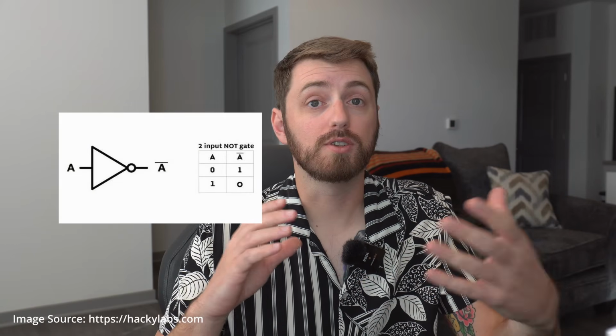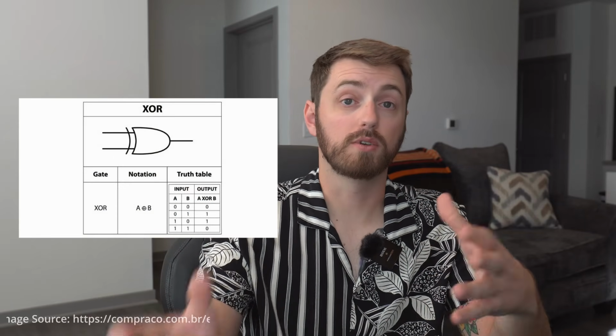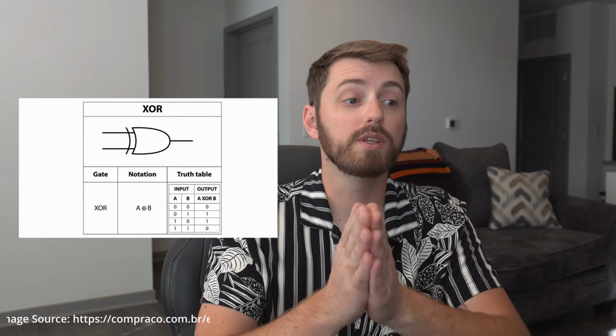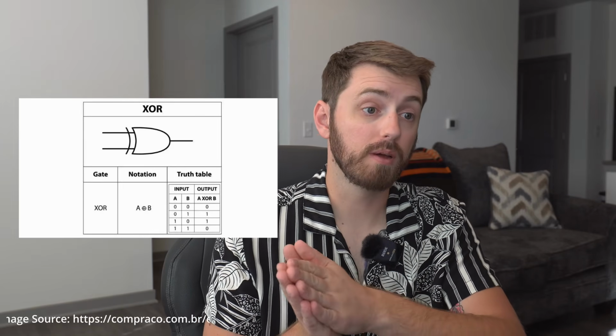The bit is held low, and it's not true. The third operation is called NOT, which basically just reverses the input. If the input is high, NOT brings the input low, or a 0, and vice versa. Lastly, XOR, or exclusive OR, it's only true if X or Y are true, but not both of them.